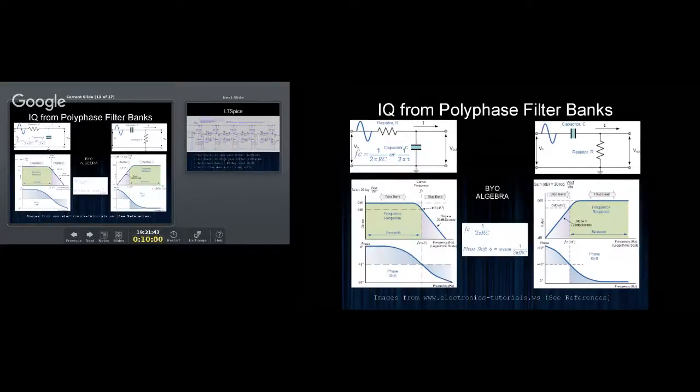So what you'll notice is that on the low pass, you have a phase shift of -45 degrees at the corner frequency. So I'm going to jump out here because the mouse isn't very good at this, but this line here, the corner frequency, you see the phase shift is -45 degrees.